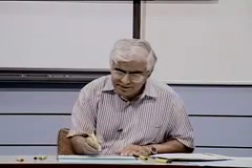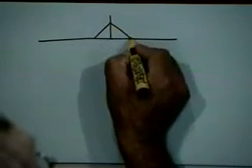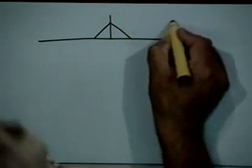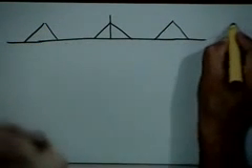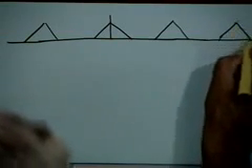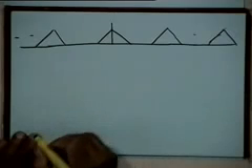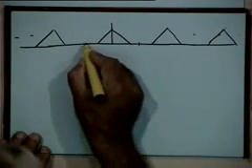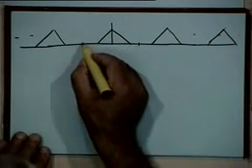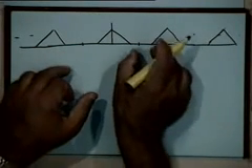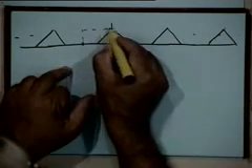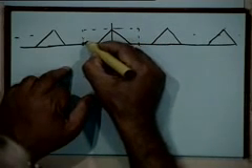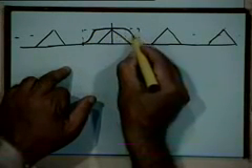Let me just recap for you if you are not recollecting. Suppose your message signal has this kind of a spectrum, and the sample signal has this kind of a spectrum. It extends up to infinity on both sides. So if you want to reconstruct this signal back, you have to pass it through a low pass filter. If you have sufficient gap between these, then you have a possibility that instead of working with an ideal low pass filter, you can work with a slightly non-ideal filter.